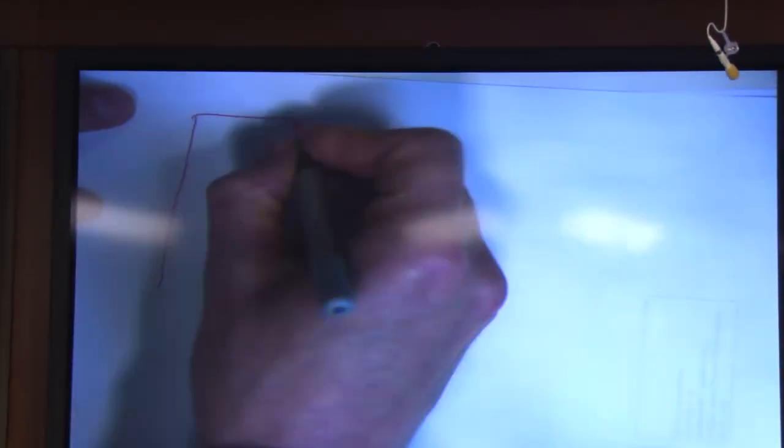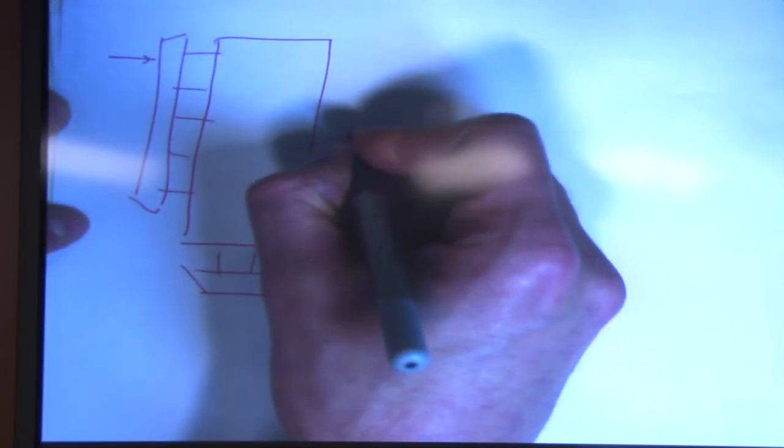So if you have a memory array that looks like this, basically you input an address, and you need to determine the row, right? You have a row decoder, and then you have a column mux over here. And let's say you have n bits over here.